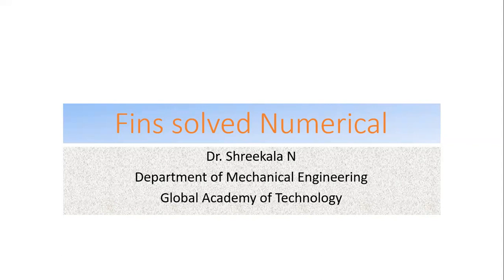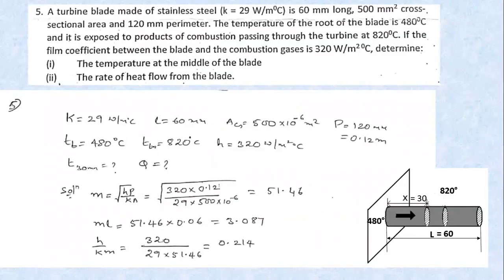Today in this lecture, we are going to solve some more numericals on fins. So in this problem, there is a turbine blade of length 60 mm, made of stainless steel and having a thermal conductivity of 29 watt per meter degree centigrade.